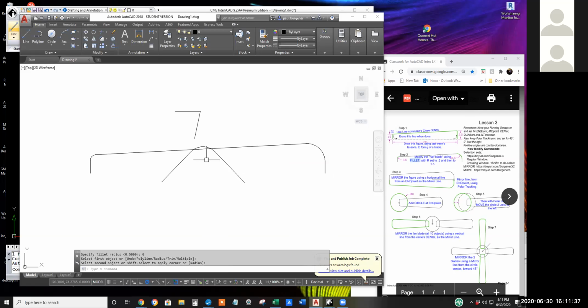By the way, keep in mind that once the arc is formed, it sticks there forever. When we learn polylines, they have a little bit of intelligence. But if I were to fillet these two lines, check it out, they go to a 0, but the original arc remains. So you gotta erase the original arc if you change to a 0 radius or a 10 unit radius, or anything.